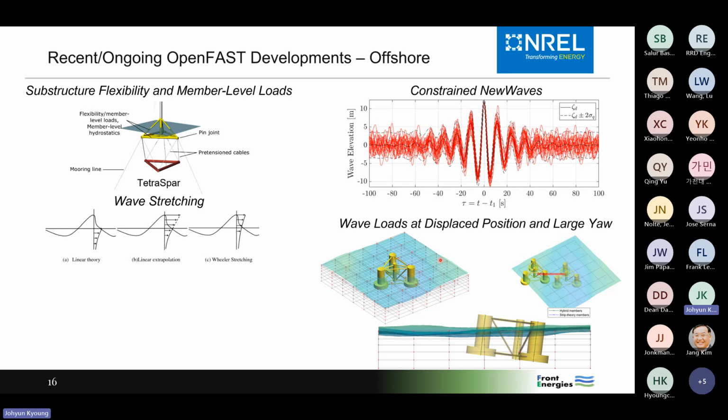But with irregular waves, the phasing is also irregular. You should do it for efficiency. Yeah, it's really an efficiency thing. You could shift it over here and then recalculate it all, but we found it better just to pre-populate a database and then interpolate it. Okay, maybe we can discuss. It probably depends on how many nodes you have and how refined you are. We found it more efficient to just pre-compute a database and interpolate.